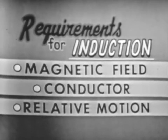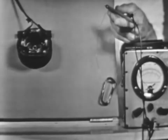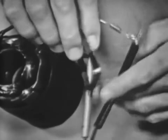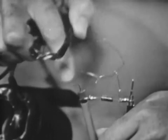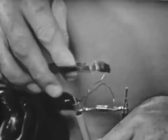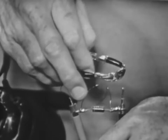We've got a magnetic field here that's rotating about the field windings. I'm going to take the rotor out of there and prove that we have induction taking place. This is a coil of wire. The ends of the wire are connected to a resistor that is connected to the leads on our PSM6. If we get current to flow in this loop, we'll have current flowing through this resistor, we'll get a voltage drop, and we'll read the voltage on the PSM6.